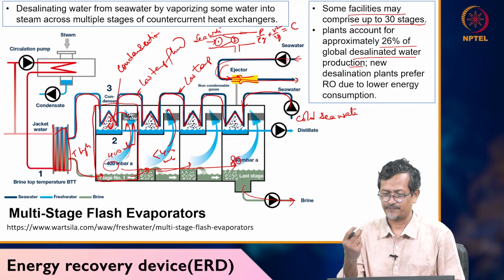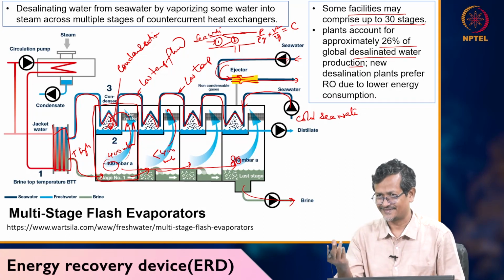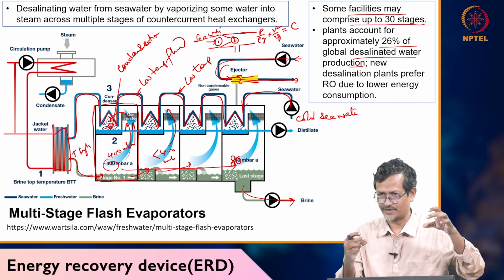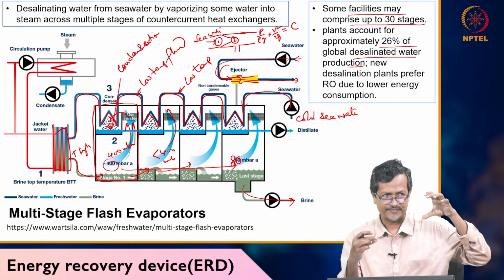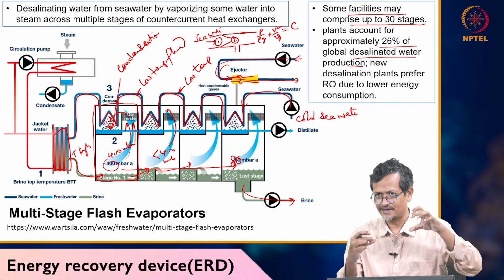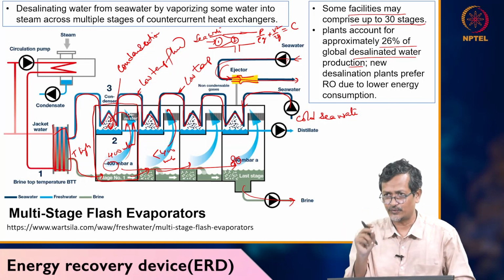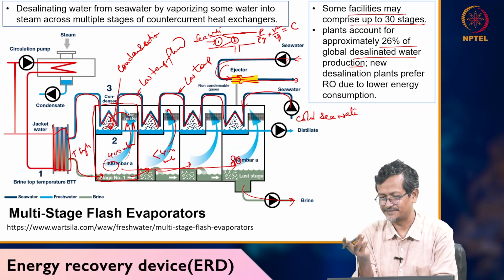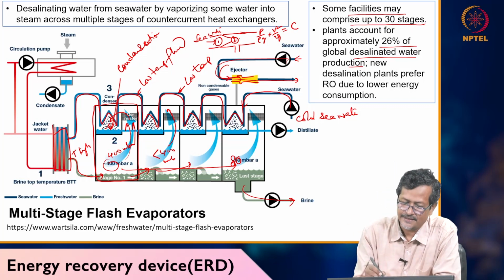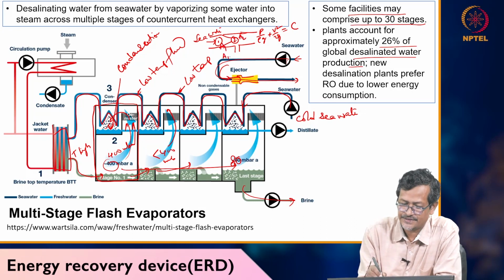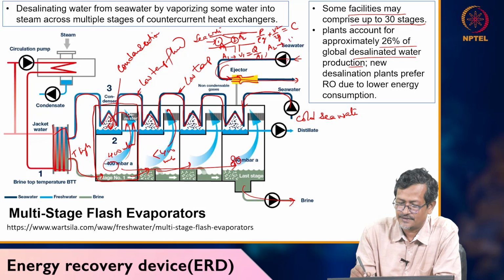When you reduce the diameter, fluid velocity actually increases, because you have to maintain the same flow rate. It is water, an incompressible fluid, and velocity will be flow rate divided by area, okay. Now, point 2 area is changed, okay, I will explain like this: area A1, area A2. So, at A1 velocity V1 equals Q by A1, and at A2 velocity V2 equals Q by A2, okay.